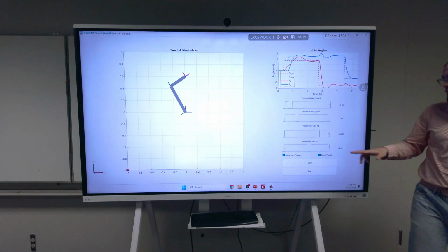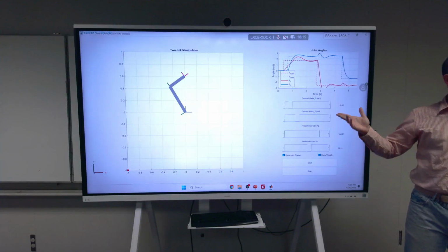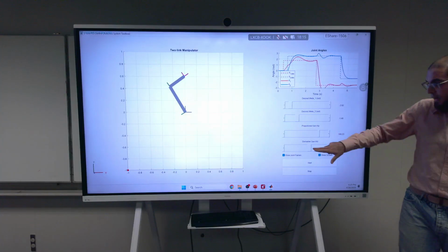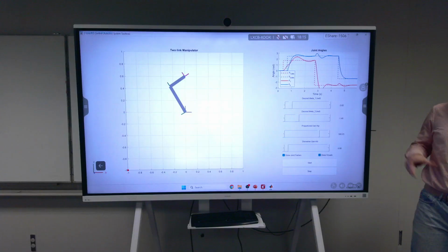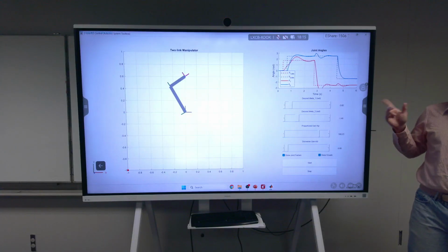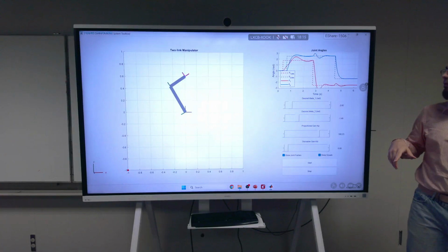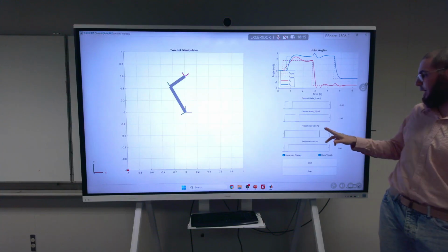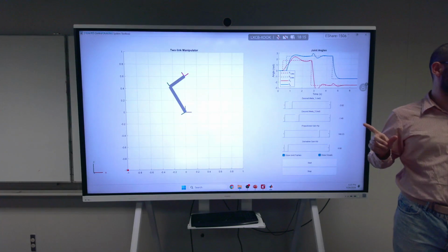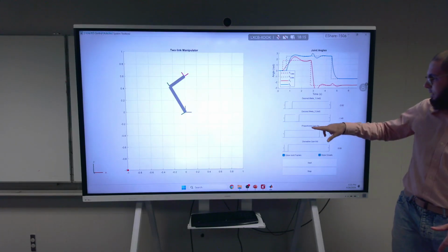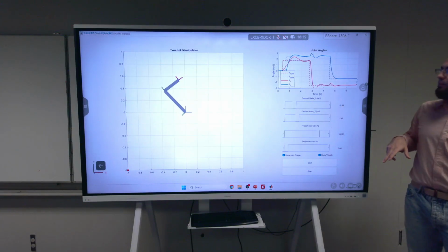If I choose the KD to be 0, do I still have stability or not? Yes. That's exactly the result that we said, right? Even if I have KD equal to 0, with a very high proportional term. Let me see. I think I did not put the friction in this simulation, so you can play around with that at home. But I don't think I have friction here, and this will not be globally asymptotically stable. However, it will be stable. What does stable mean in that sense? It's not going to be pretty, but we'll see.